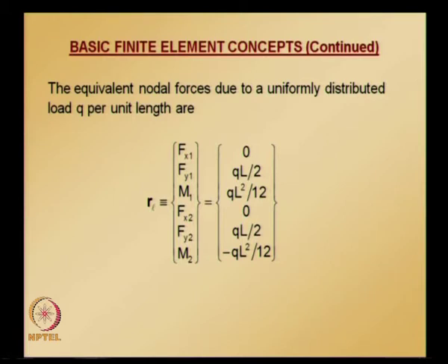So, we have the element equations for a frame element in the local coordinate system, but usually this frame element will be arbitrarily oriented in space if you take any structure. So, we need to look at the transformations and other things. So, for proper assembly a global xy coordinate system is chosen for the entire frame.